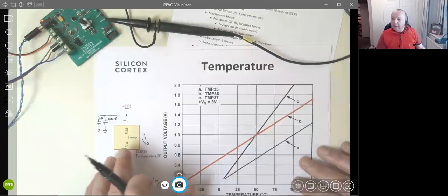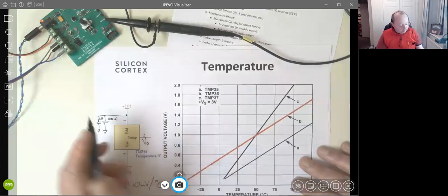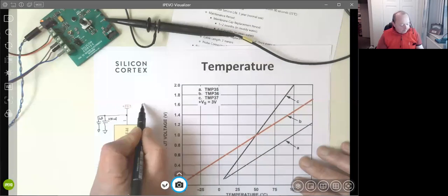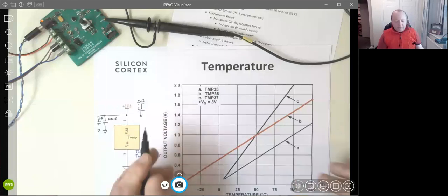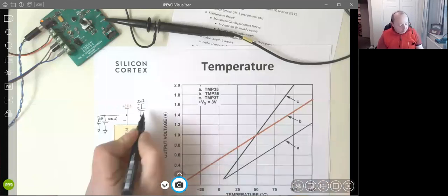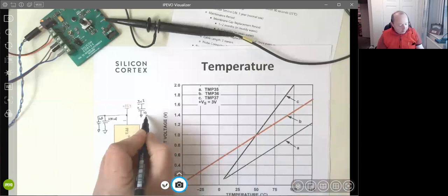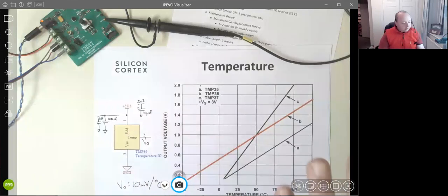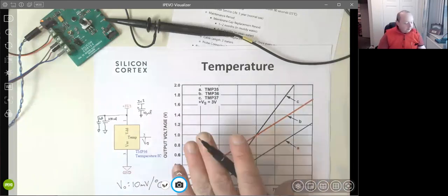But if you've got analog, I'll certainly be probably adding a bulk capacitor. By bulk capacitor, I mean a large value, somewhere in the order of about 100 microfarads on my designs. It's all about trying to keep the power supply smooth and clean.